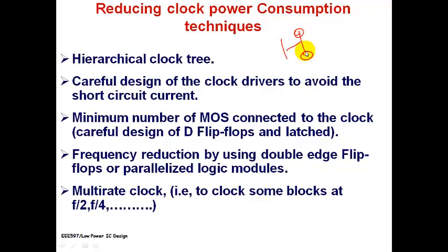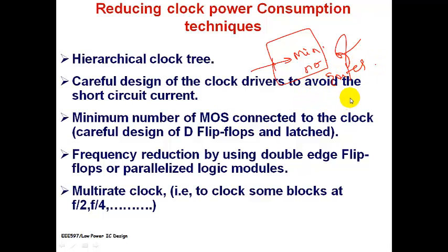When I consider this H clock tree, here I am having some load and here I am having some load, and all these loads are actually what? The flip-flops and the latches. As far as possible, try to reduce the flip-flops and latches, the timing elements. And even if I have one flip-flop, see to it that a minimum number of gates, transistors, individual switches, are operated by the particular clock signal. We have got to see to that.